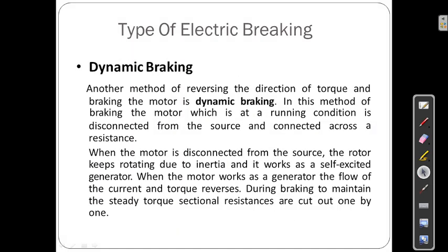Then dynamic braking. The other method of reversing the direction of the torque and braking the motor is dynamic braking. In this method of braking, the motor which is in a running condition is disconnected from the source and connected across the resistance.